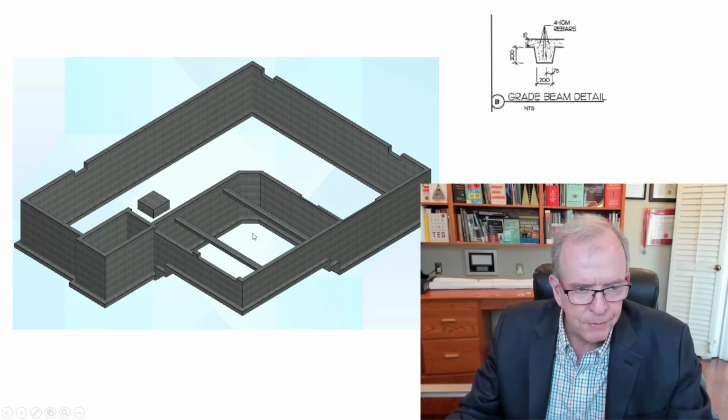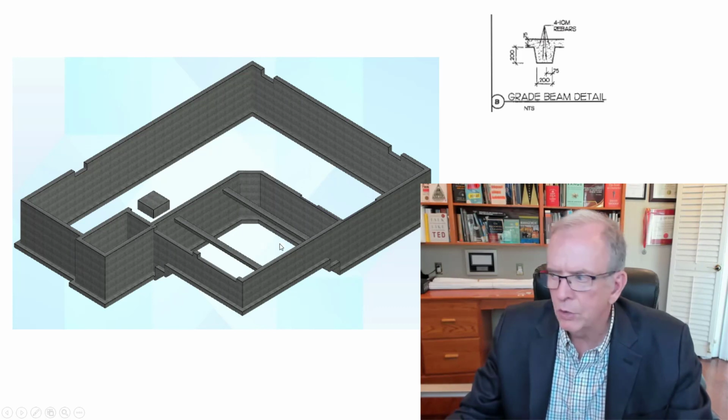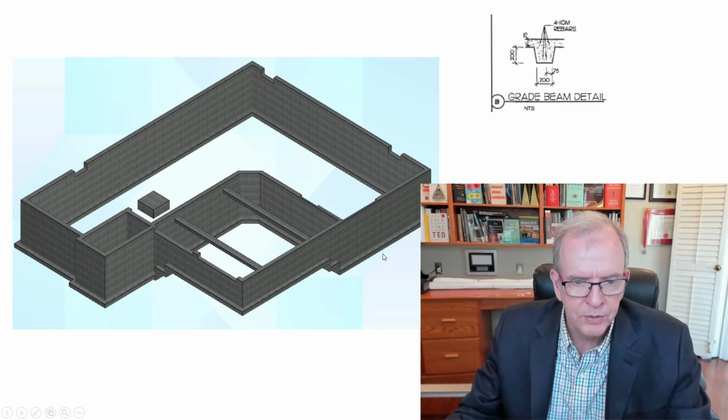Well, you don't have a basement underneath here, so there's no need to go down this deep, because in this particular case the rest of the house is probably about 7 feet down. And here you only need to be 4 feet, or 1220, below grade, below the frost line. So what they do is they step this down 4 feet, then down to wherever you've excavated.